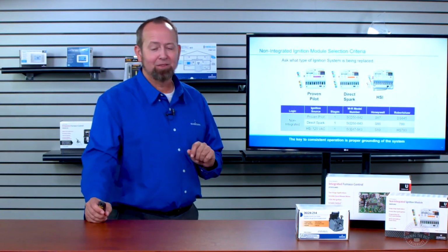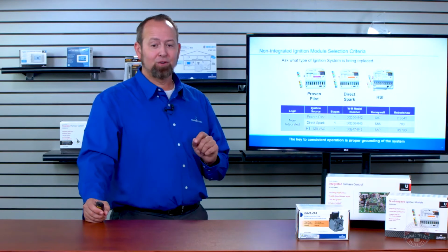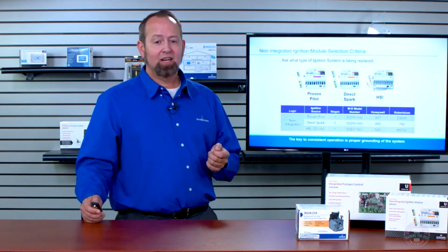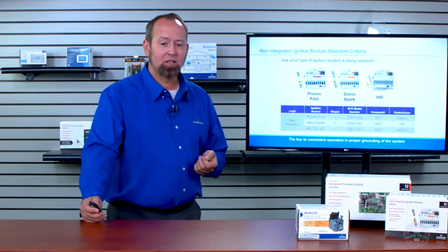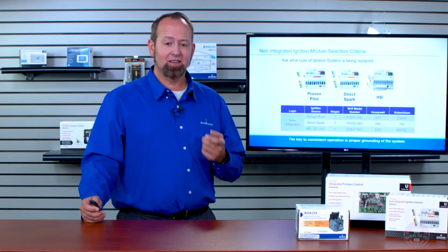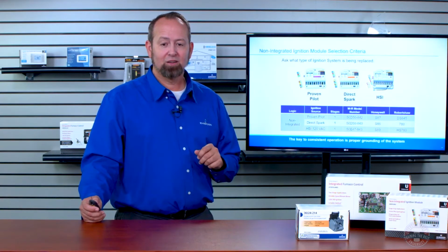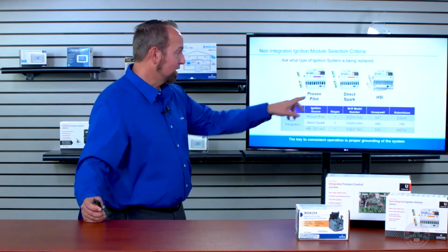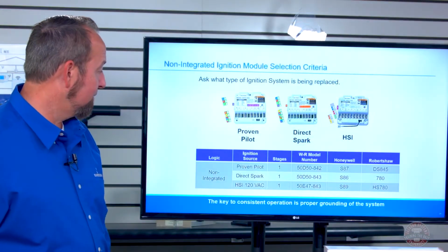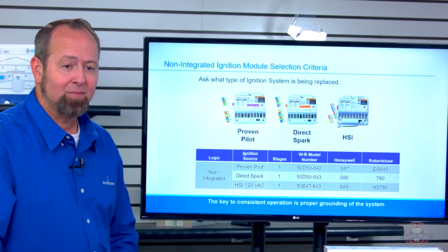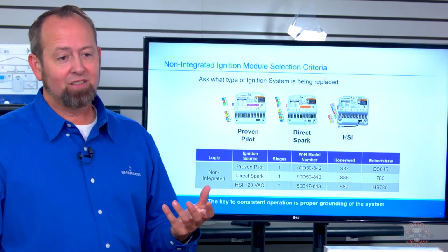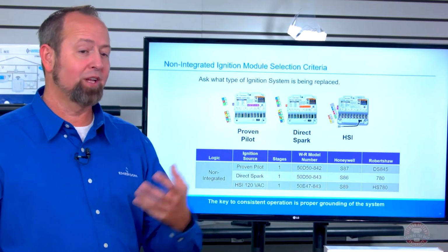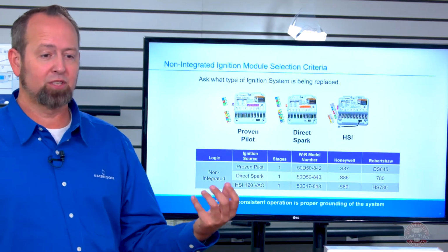We still have a lot of furnaces that use the direct spark module, and this module does work with those direct spark furnaces. Very popular module, the 50D843, but these, again, they're modules. They're non-integrated. They're only half of the control system of the furnace.